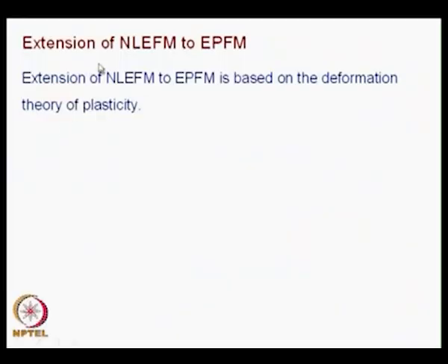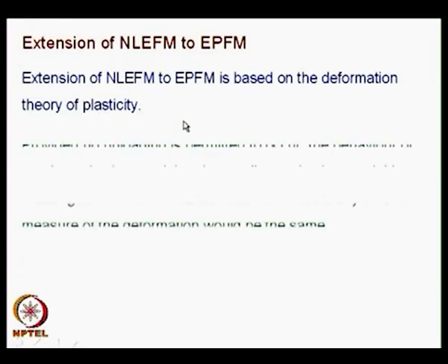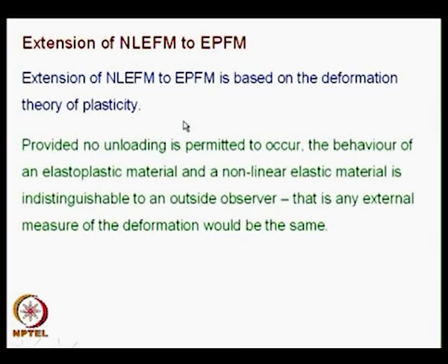So, we want to graduate from nonlinear elastic fracture mechanics to elastoplastic fracture mechanics, and this extension is based on the deformation theory of plasticity. And we have seen unloading creates the problem.